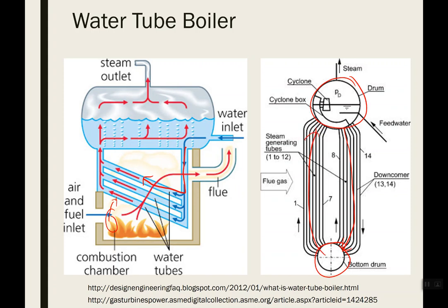It's also a way to collect kind of nasty stuff, and you can do what's called blow down. You can start sucking some of your nasty fluid out of there and dump it down the drain or whatever you're going to do. So typically, to increase the rate of heat transfer, if you step inside one of these, what you'd actually see, you'd see a big room, and then the walls would be almost entirely covered by tubes. So taking advantage of all that surface area to maximize exposure to the flame and therefore the rates of heat transfer.